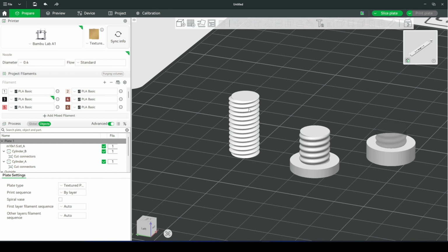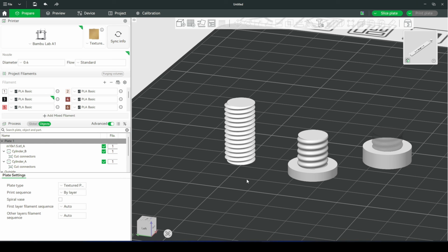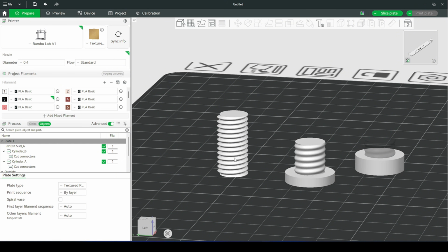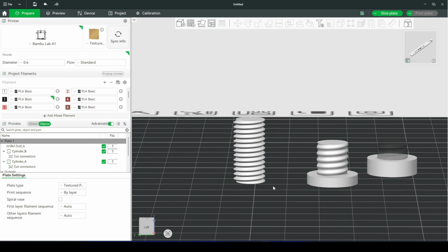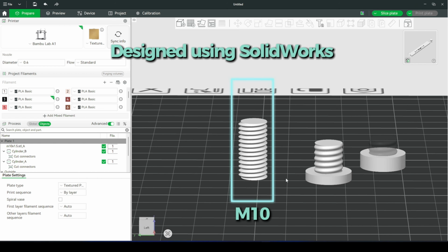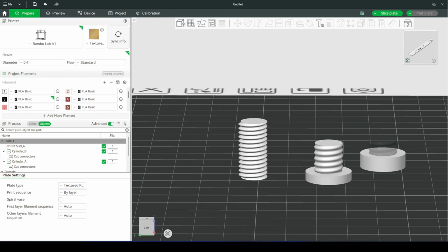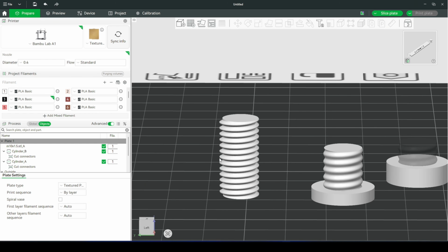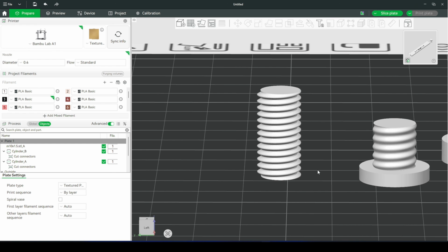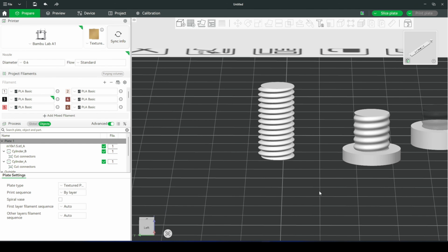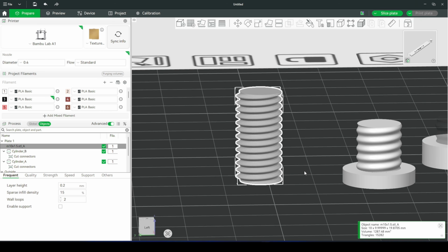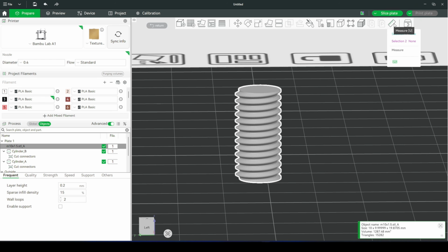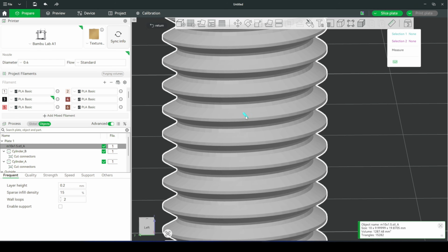To make sure we are completely on the same page, and to test this scientifically, I designed a specific headless test bolt inside SolidWorks. The very first thing we need to understand is that in the real engineering world, every single type of standard bolt and nut has a fixed, dedicated pitch. For example, for a standard M10 bolt, the ISO standard pitch is exactly 1.5 millimeters.